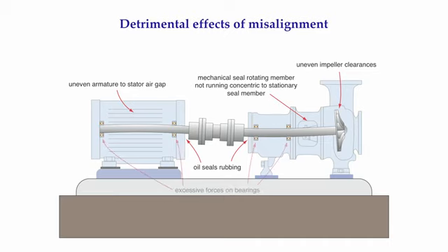In addition, the loads on the bearings are increased and on some bearings decreased to the point where the shaft becomes unstable, producing a whirl condition. Because the shafts are elastically bending, the possibility of cyclic fatigue failure is increased. The other major thing that people do not realize is that this illustration shows why you should never keep a coupling engaged when attempting to align machinery.